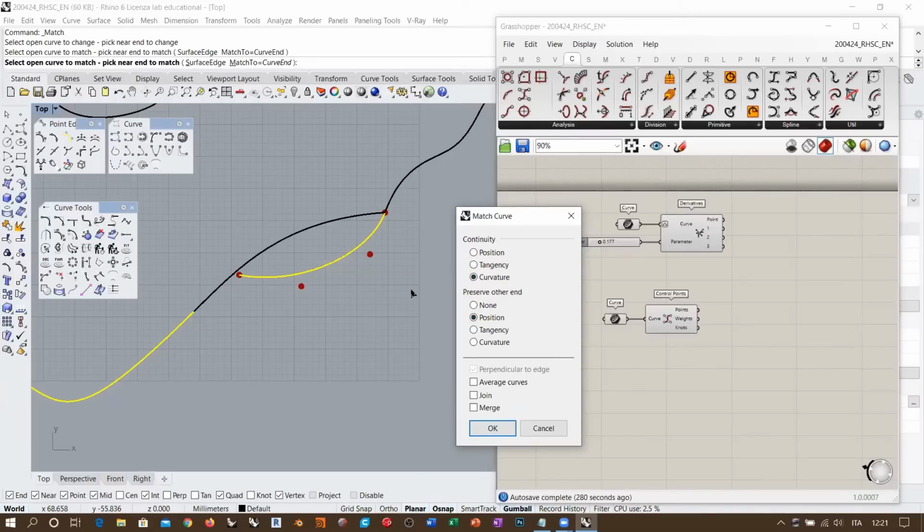But there are commands that cannot do this. So you need to create the right topology in order to have Rhino adjusting the continuity to the desired level. And in that case, if you don't provide enough control points, you simply cannot adjust both continuities on both ends to the desired level because you lack the right amount of control points.